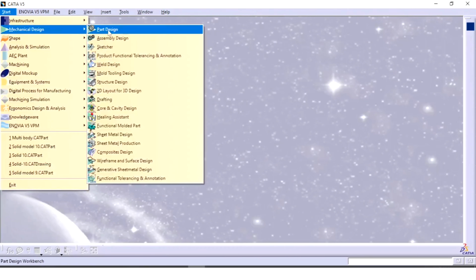What are the advantages? It provides an organized approach to modeling complex parts. Solid features within a body can be hidden independently of the rest of the model. Groups of geometry can be deactivated by deactivating the body. Some group of geometry like this one, you can deactivate.